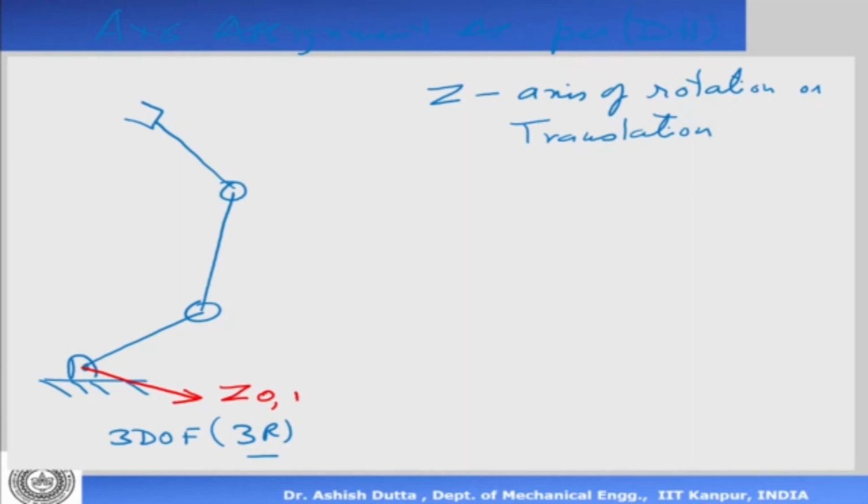Okay, so it basically means that I'm assigning my axis 1 to the first link. So this is my second, Z2, this is Z3. Okay, so this is the origin which is assigned on to the link 3, link 2, and link 1. Okay, and Z0 is the one that does not move. So the next thing that we need is to figure out where is the x-axis.